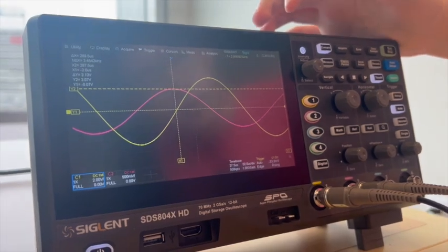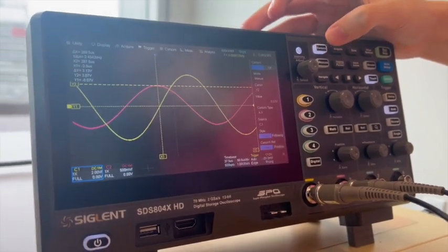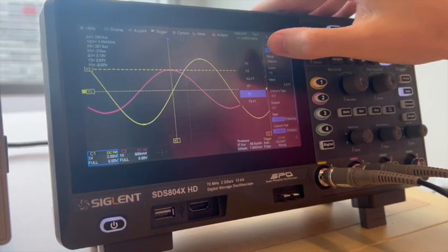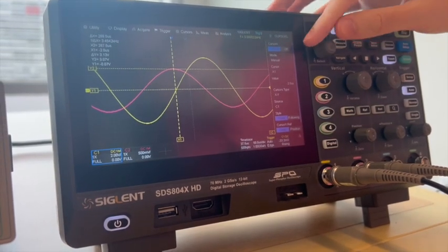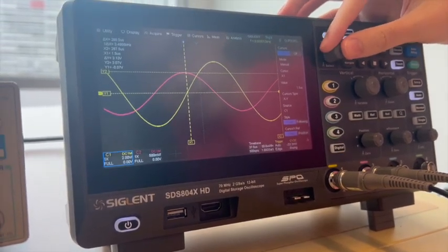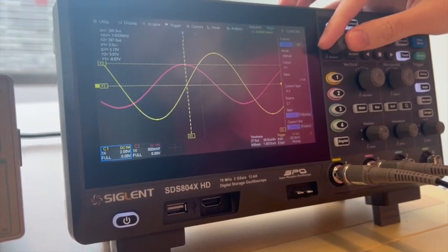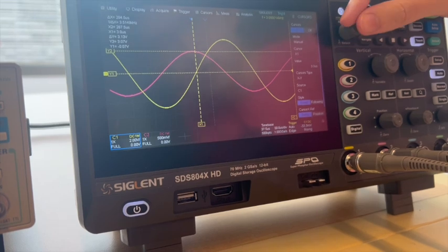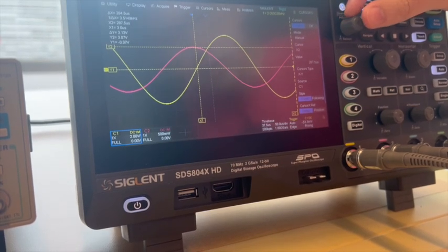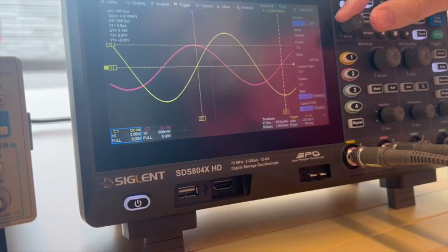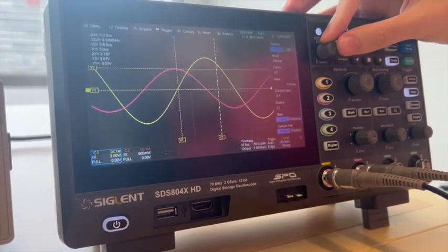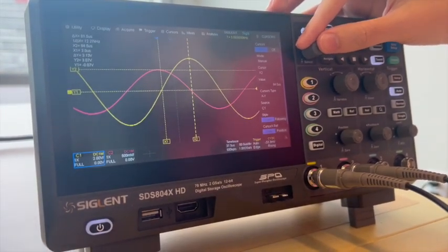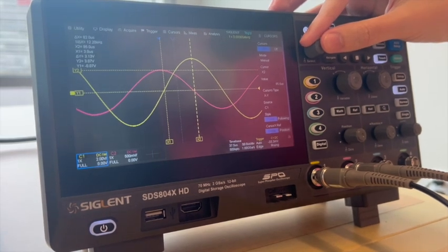So how do we get our peak to peak? Well, we are going to turn on our cursors, which I hope you're all familiar with now. And we're going to set our first cursor to our input line. Right, so we want it right in the middle of the trough. So right in the middle of the pink. I believe that looks good. And then we want to get our second cursor, and we want to put it on our output, or on our input. We put the first cursor on output, second cursor on input. There we go, that looks good.